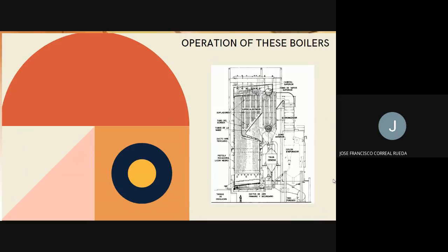Now I will speak about recovery boilers and the description of their operation. Recovery boilers are a special type of water tube boiler that meet the following characteristics. They are stationary with an internal ignition furnace, two drums located transversally, a simple gas passage and natural water circulation.